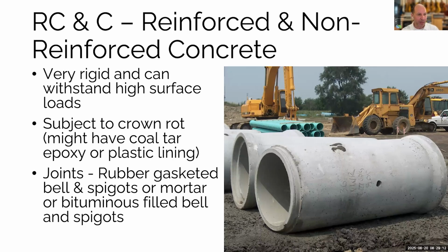The way these are stuck together, you can kind of see the two pieces of pipe that are there. They're oriented in different directions. The one in the foreground, that front end is the spigot. That's the narrow end. Around that will be a big black rubber gasket that slips into the bell end, which is the other end. And they're just basically put together and held in place by friction and the installation, and that's what forms the seal. The bells always face uphill so that the water runs over the seal and not into it, so the fluid going through it isn't trying to push the pipe apart.